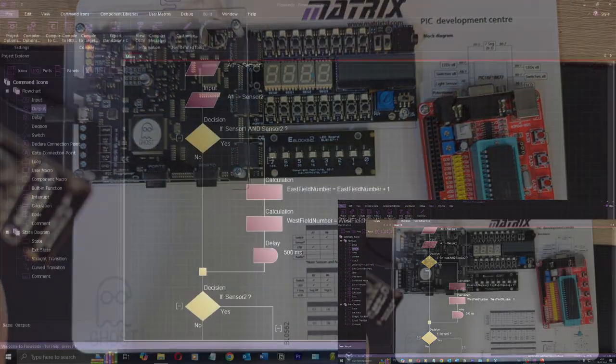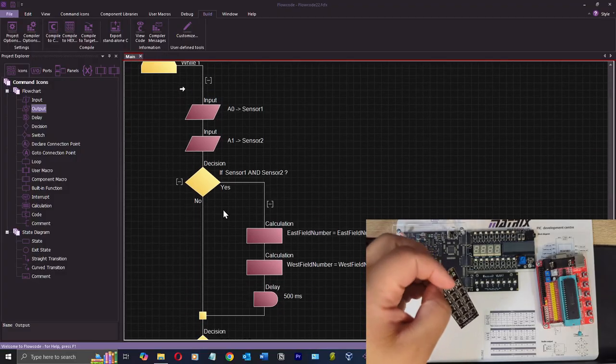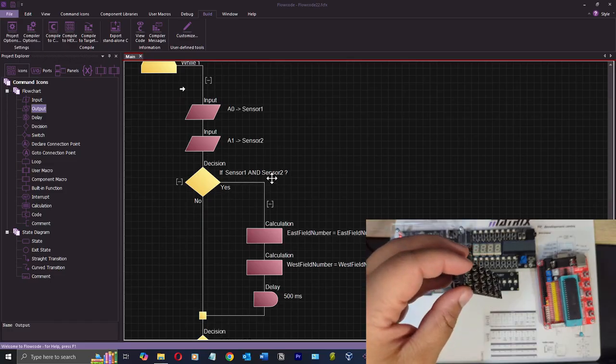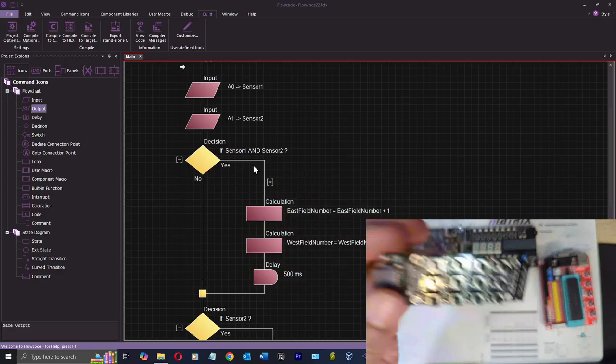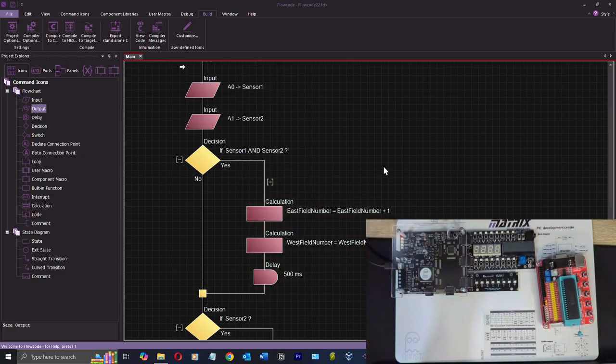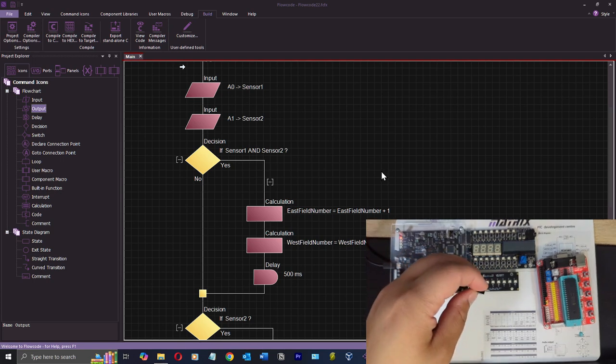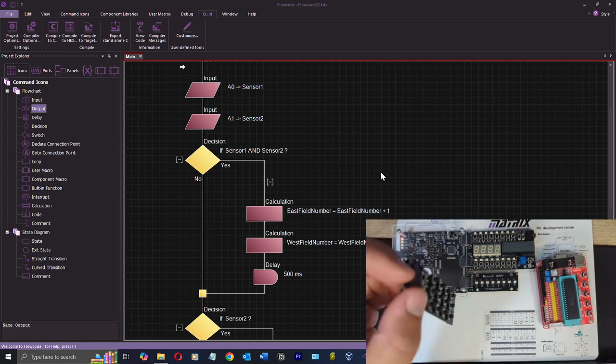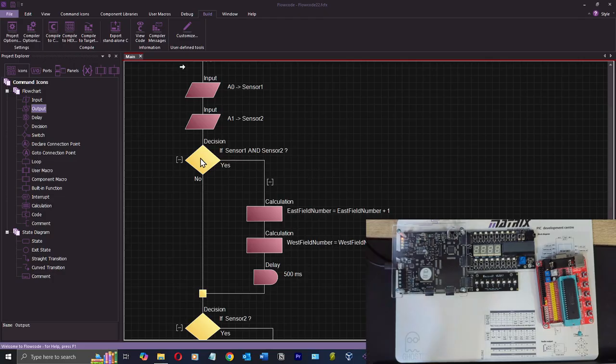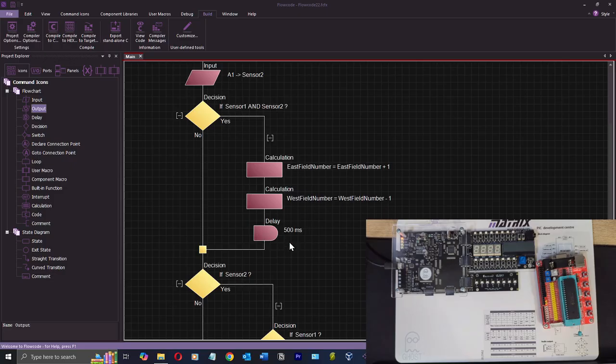I've lost motivation with this, and if it doesn't work first time... I'll probably figure this out, because I'm sure one of the experienced guys at work is going to see this and be like, yo, what are you doing, you dumbo? Use this thing. And again, like I said, all my push buttons should be interrupts. If they're interrupts, this whole thing works fine. But whilst the microcontroller is in this delay mode, it isn't reading anything else.